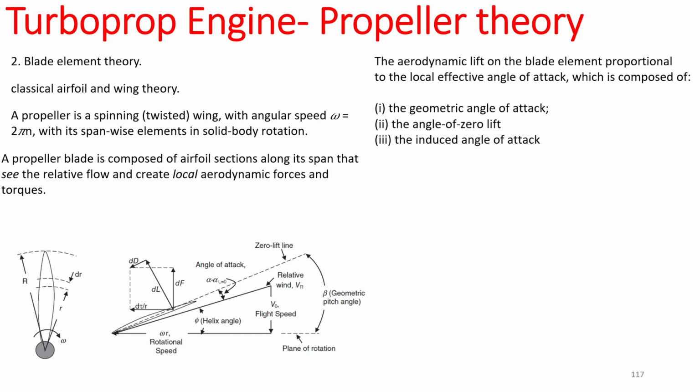I'm not going to go through the derivations, but eventually you can find the force and the torque of the blade, based on the lift and drag that is being exerted on the blade by the flow. And keep in mind that we are talking about one small element on the blade, right? So we have the derivative of force dF, which is going to be dL cosine of phi, and phi is the effective angle that your blade makes with the plane of rotation. All of these should usually be given. And then you can find the small element of torque as r multiplied by dL sine of phi plus dD cosine of phi.